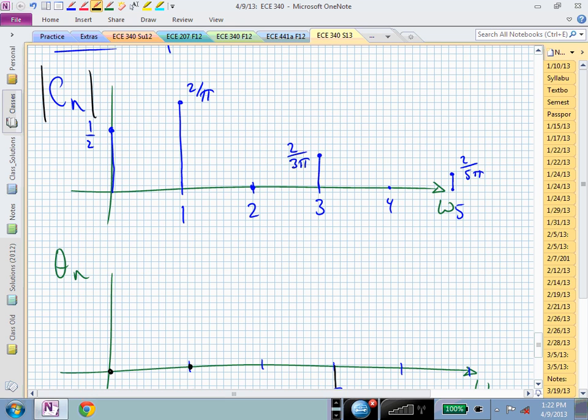And in this case, you're not going to see anything. You would say, oh, the second harmonic is giving me nothing. And if you did the analysis, you could go, that's exactly what I expected. I'm now filtering x of t, and with the second harmonic, or 2 radians per second, as my bandpass filter, I shouldn't see a thing at the output. Good. That's exactly what I expected.